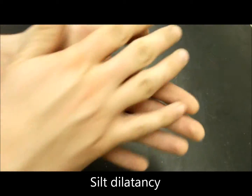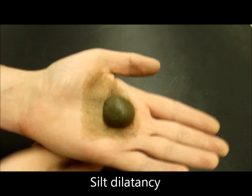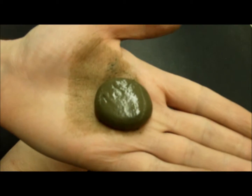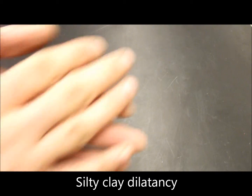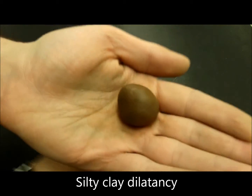Dilatancy. Dilatancy measures the expansion of a soil in reaction to shear deformation. To simulate this in a lab setting, we mold a 1-inch diameter ball of soil, adding water if necessary to facilitate the process, making sure the soil is soft and smooth, but not enough to be sticky. The ball is then placed in one hand and the surface smoothed out with a spatula.